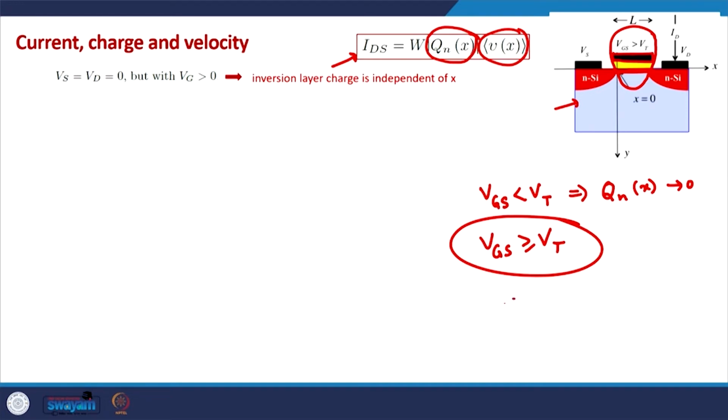So, if the capacitance of this capacitor is Cg, the gate capacitance of the MOSFET, which is approximately equal to Cox in most of the cases. While we do not want to deal with the details of the capacitance in the MOSFET, we generally take Cg to be equal to Cox, but ideally Cg includes Cox and the depletion capacitance of the channel. If we have a capacitor with capacitance Cg or Cox, and we know the voltage applied across it, we can easily deduce the charge that appears on the plates of the capacitor.